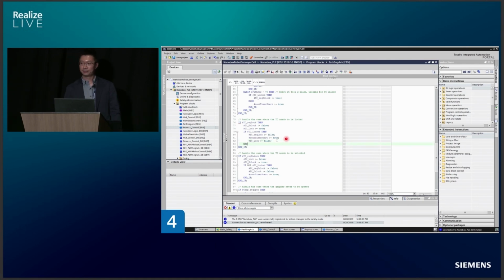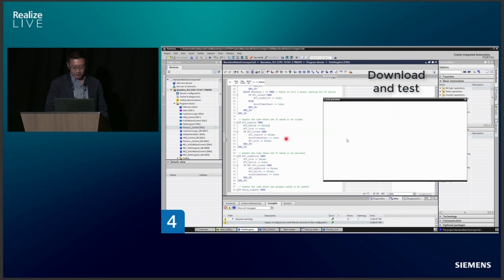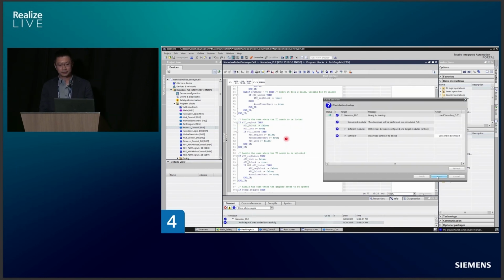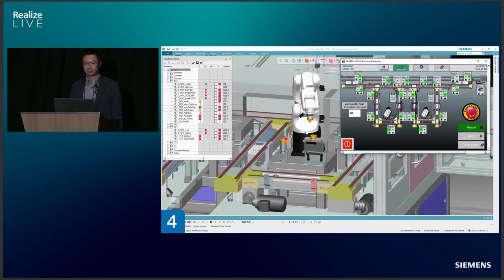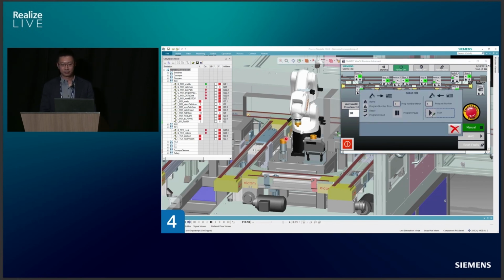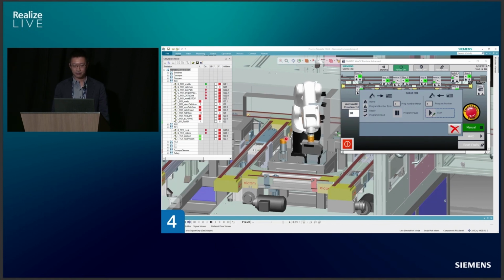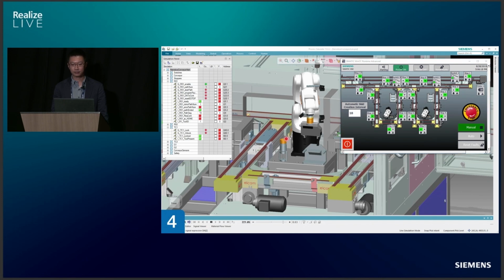Real world scenario, that has happened. That's a common thing with the robot, right? It's going to change the end of arm tooling. You've got different parts coming in, but there's a dependency on the PLC. The PLC has an influence. When I first saw that, I was like, isn't the robot taking care of all of the end of arm tooling? For the most part, but the signal controls the release of the tool. So little things like that can end up causing you a lot of damage in time if you don't catch it, right, in time. So.